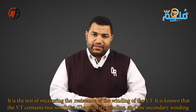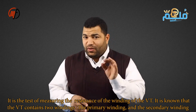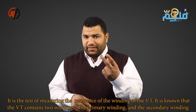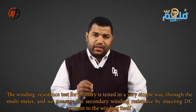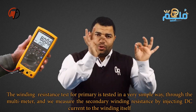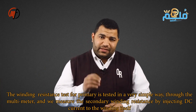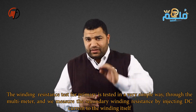The winding resistance test measures the resistance of the VT's windings, which include the primary and secondary windings. The primary winding's resistance is tested with a multimeter, while the secondary's is measured by injecting DC current into it. This generates a voltage across the winding's terminals, which is measured with a voltmeter. Using Ohm's law, the resistance is calculated by dividing the voltage by the current. This process helps evaluate potential damage to the winding.